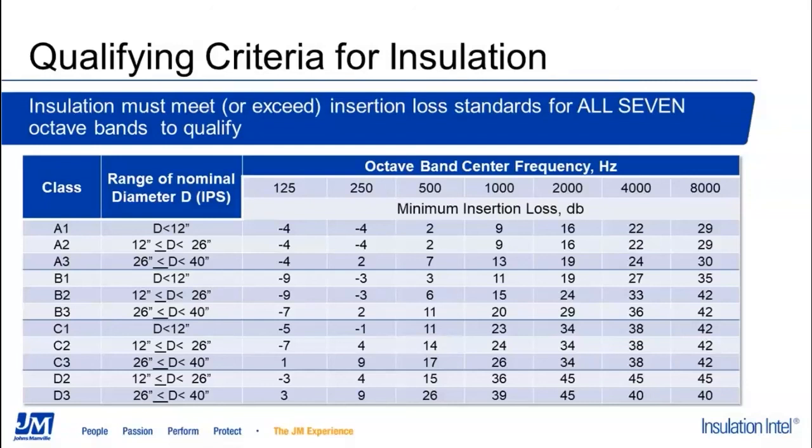And something to point out that we mentioned before, we've got a couple of negative numbers. Those are real numbers on your screen. Those are more of an understanding that ISO in the industry has come to when it comes to those low wave frequencies. The low frequencies have a tendency to behave oddly just because of the nature of the wave itself and the inconsistency. So you sometimes have, even if you're putting proper sound absorbing or any other acoustic insulation on a system, you will have some interesting numbers, and ISO has identified that and incorporated that into their standard.